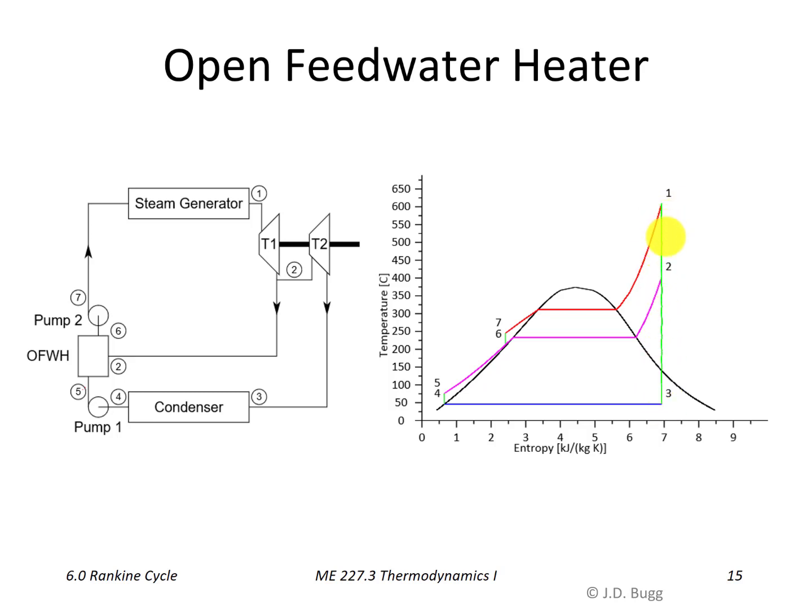And notice there's no reheat, so we don't come down here and then reheat and come down like we did when there was a reheater. We're just extracting a portion of the steam at that point. So for every kilogram that goes through this turbine, perhaps only 0.9 kilograms will continue on through this turbine, and the rest will be extracted to go to the steam water heater.